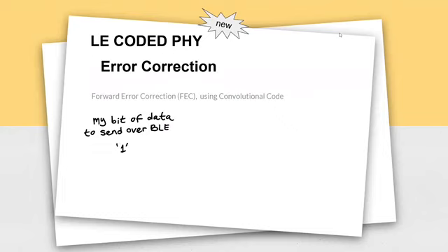How does it do it? Bluetooth 5 uses coding, a set of rules to convert information. Coding theory is a science field studying data compression, cryptographic coding, error control, and more for data transmission and storage. Hence, coded PHY. The LE coded PHY has forward error correction by using convolutional code in order to correct errors. More about this in the links that I will add at the end.